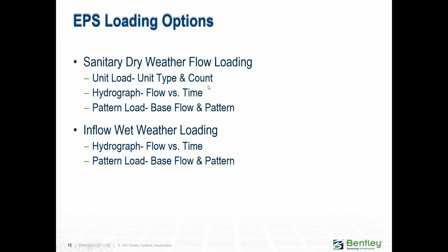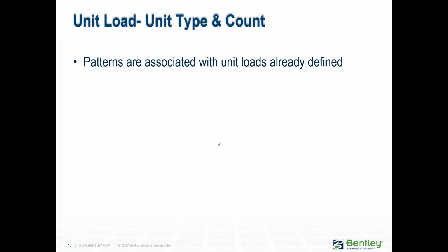So if you have measured the flow, you would input it as flow versus time. And pattern load is your base flow applied and a pattern that you apply to it. And typically for rain-derived inflow, wet weather loading, if you have measured the flows, you can input a hydrograph, or you can also input a pattern load.